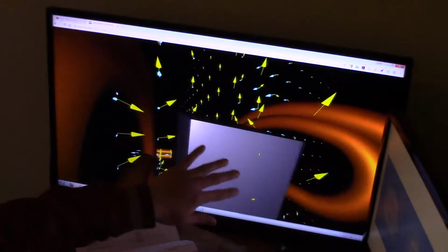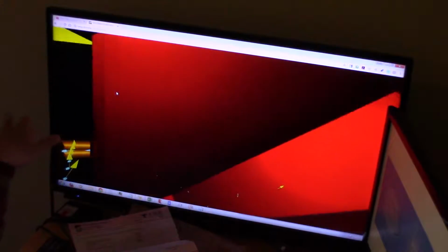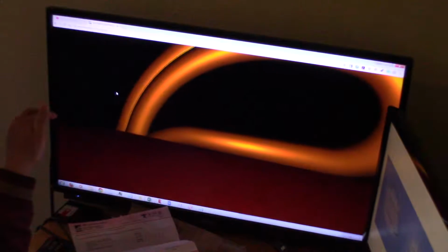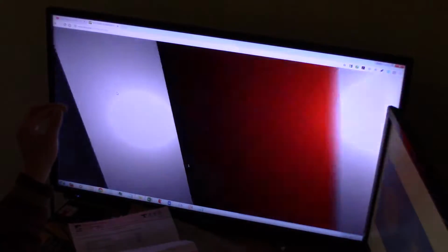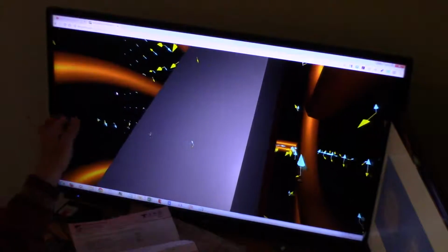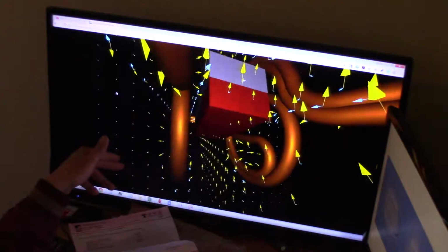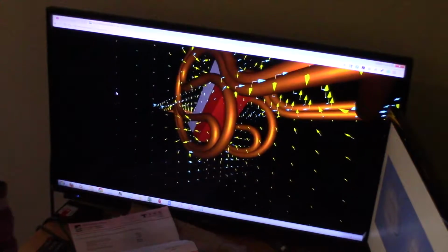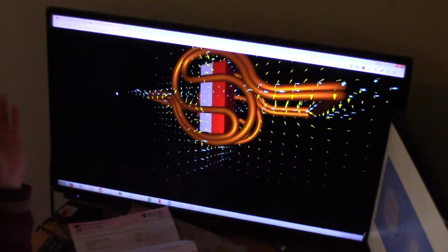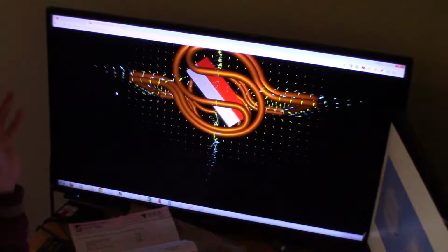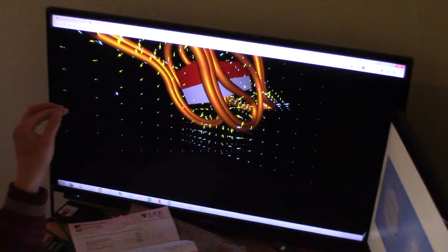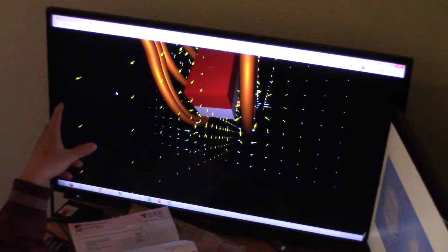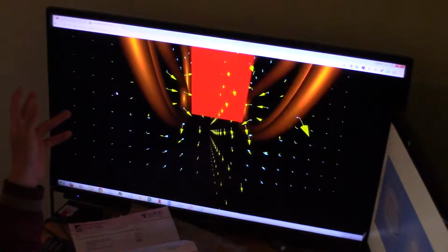Okay, so all these arrows here represent only those magnetic fields and magnetic vector potentials of the current. It is not factoring in the magnetic fields and magnetic vector potential due to the magnet. Now the magnetic vector potential is a vector field, and you can take the curl operator on the vector potential to get the magnetic field.